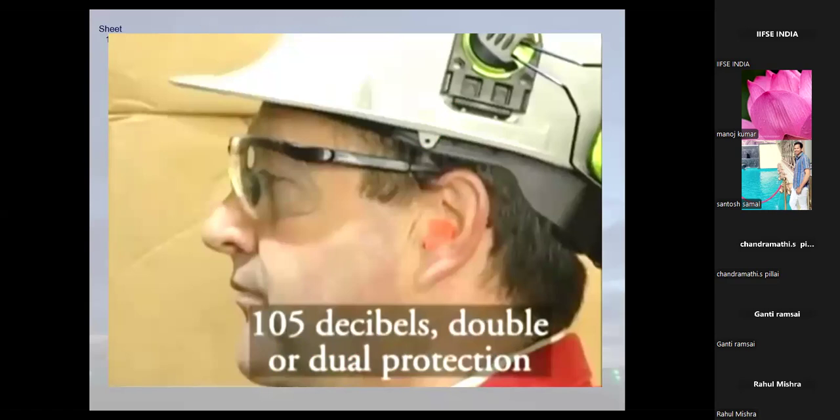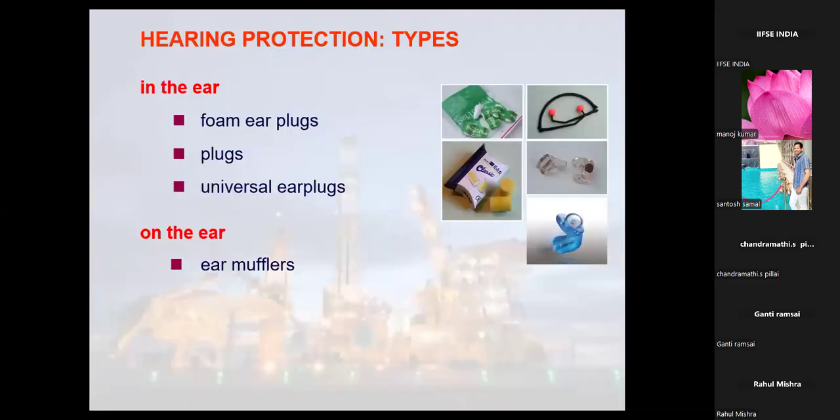Dual protection means both ear plugs and ear muffs should be worn. It is not single, either the ear plugs or the ear muff. If it is 105 dB or more, then ear plugs in combination with ear muffs should be worn.